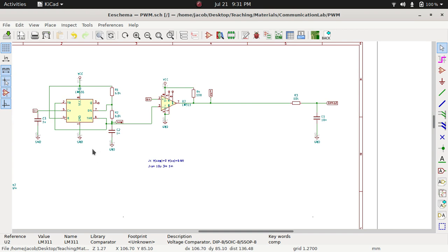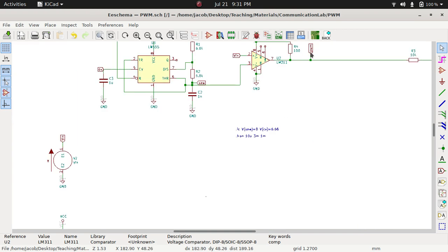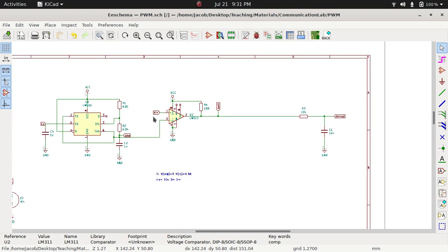And so I am labeling some of the nodes. One is this CV node and the other is this SAW node, both for this initial condition setup. And then the VIN node where the modulating signal is provided, the PWM output node, which is VPWM, and then the demodulated output. I am labeling all these nets so that it will be easy for me to show you these waveforms in the post simulation waveform viewer.